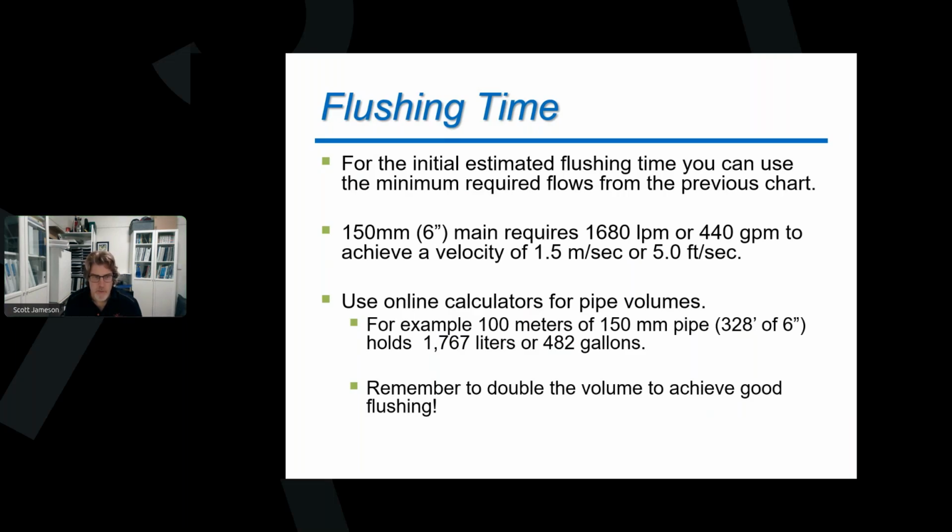1,767 liters, or 482 gallons. So I can look at that right away and see, hey, that's roughly about a minute that I can discharge that whole volume. And so I've got to remember, though, I need to do that twice. So from here, I can say, at this flushing point, I'm going to have to run it for a minimum of 2 minutes.